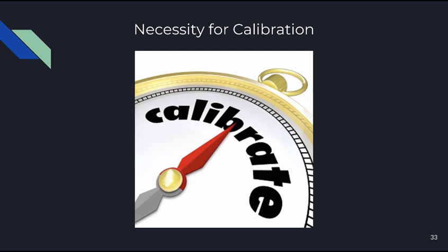During use, however, its behavior will gradually diverge from the stated specification for a variety of reasons. Such reasons include mechanical wear, and the effects of dirt, dust, fumes, and chemicals in the operating environment. The rate of divergence from standard specification varies according to the type of instrument, the frequency of use, and the severity of the operating conditions. However, there will come a time, determined by practical knowledge, when the characteristics of the instrument will have drifted from the standard specification by an unacceptable amount.